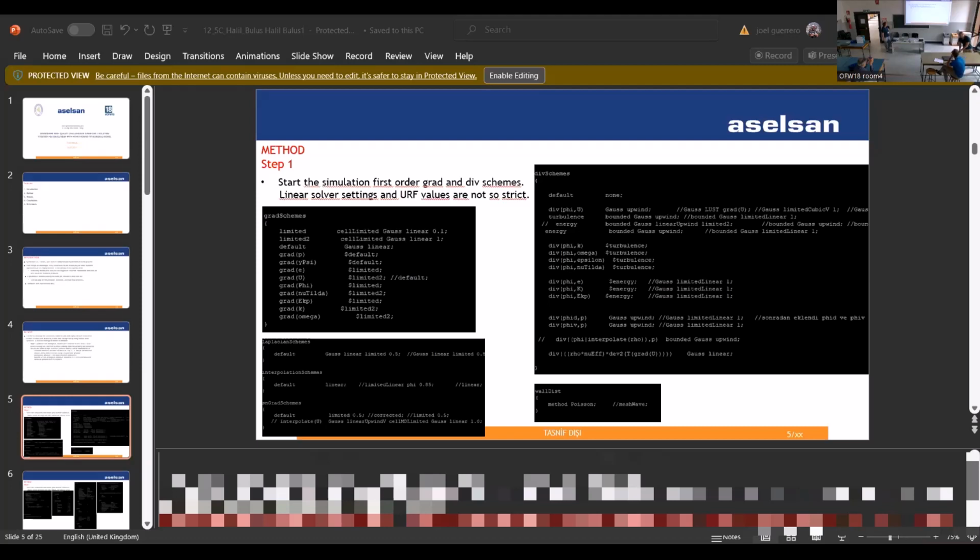So when you use the differential gradient limit, and I have experienced it a lot, that's why I'm preferring it. And we switched the discretization and gradient numerical schemes to second order. As you can see from the screenshot, that's why I put it here. And now to show the results.